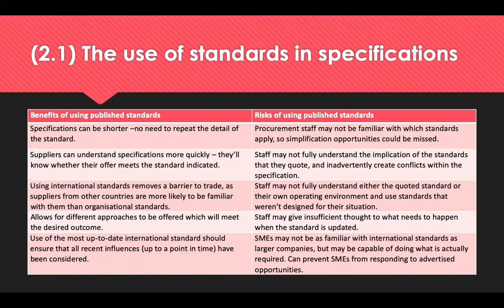Standards in the specification will cite a number of different dates of publication to ensure that everyone's referenced in the same way. They may be updated from time to time, and this can cause confusion if it occurs in the middle of a contract. Two options for referring to standards in contracts are to fix the date of the publication of the standard at the date of contract, or state the publication date as the standard to apply at the commencement of the contract, but include some wording that requires compliance to any subsequent additions.